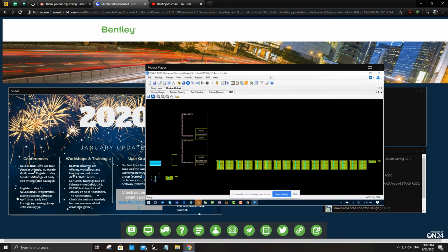You can view your local coordinate system. You can change the direction of your local z-axis if you need to. I typically would do that before I added any loading to the wall or reviewed any results. So you can do that and affect that local coordinate system once your mesh is within your system. You don't do that in the parametric model area. You do that in your main STAAD.Pro interface after it's committed to the input file.